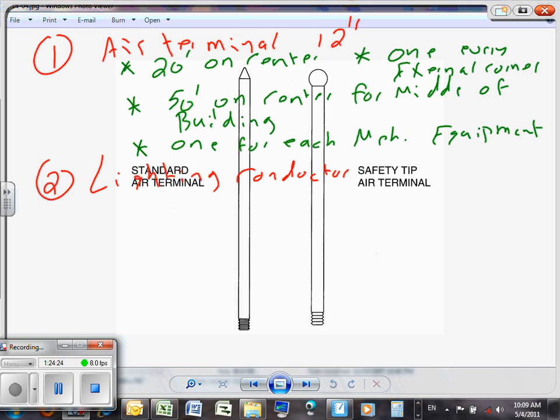It says 59 kcm. So you need minimum 59 kcm copper. Let's use 59 kcm, or if you're using aluminum because you're cheap, 98.5 kcm AL or larger. So make sure when you put your dotted line, guys, you keynote them. How are we going to keynote them? We're going to annotate them.